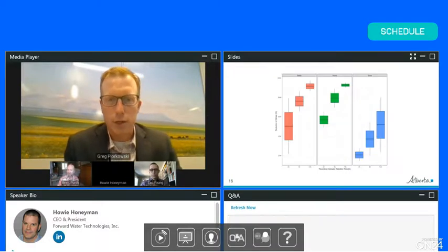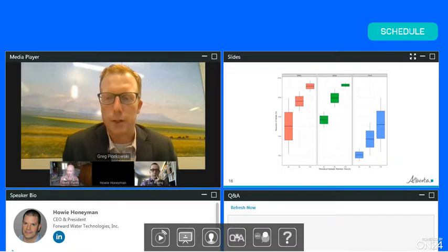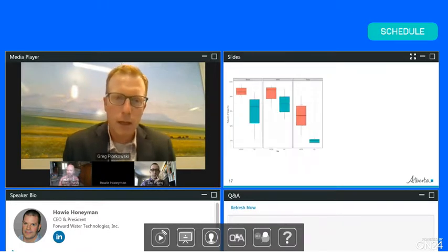What this graphic is showing is the % reduction in nitrate, and I've broken it down into barley versus hemp versus wood. What we can see is that the agricultural residues range from about 50 to about 90% removal, depending on their hydraulic retention time, which is greatly higher than what we observe for wood. So we are seeing that the agricultural residues have a much greater performance with respect to nutrient removal than our wood.